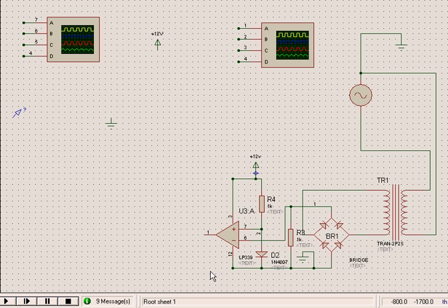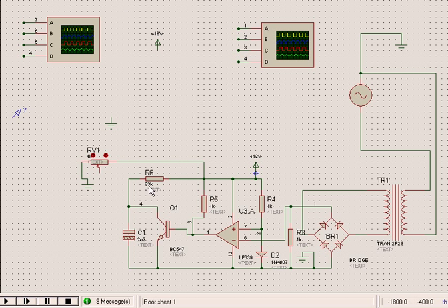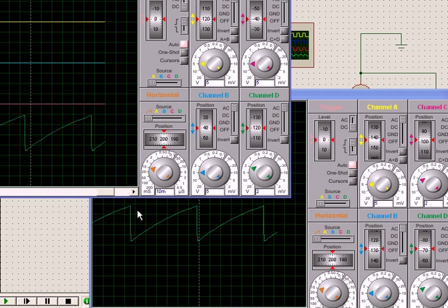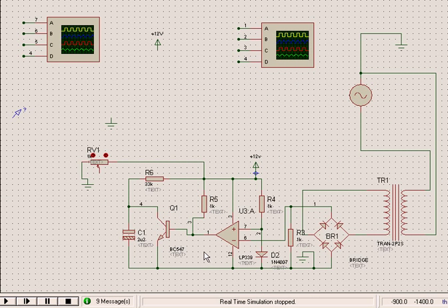Then we go over to one operational amplifier which is used in comparator mode. This we have discussed in our other audios, of how we compare the input with the pulsating voltage and then how we get the output. Now if you look at this, the output we achieve is in this fashion, and this particular output, which is the zero voltage output, is given to this transistor, which develops the ramp voltage or the sawtooth voltage.